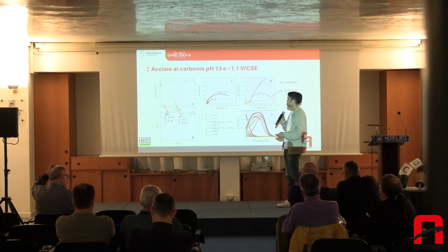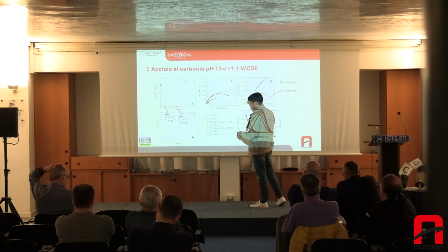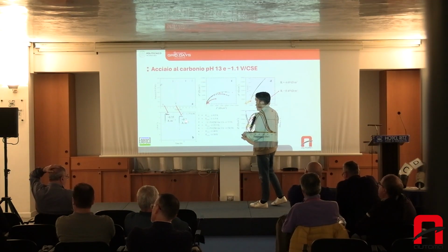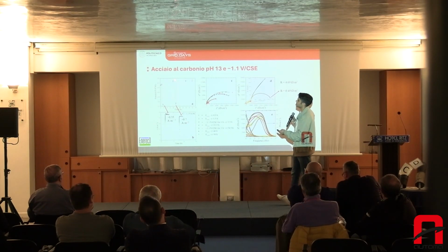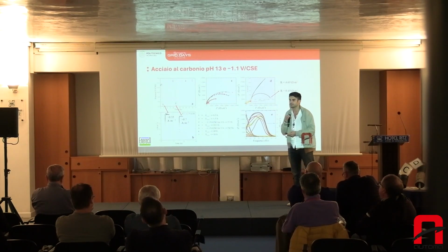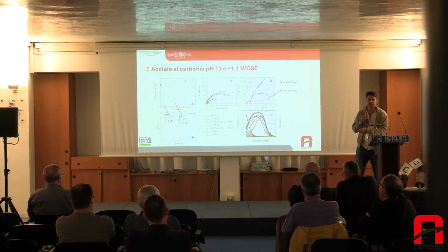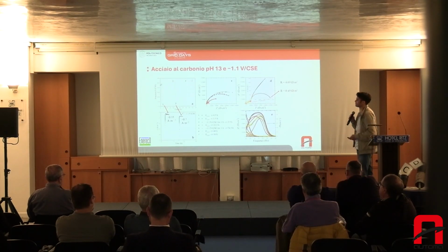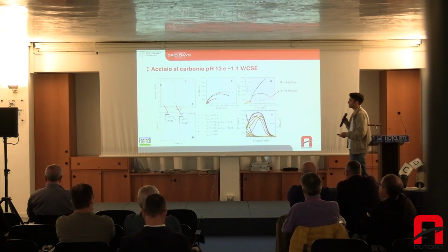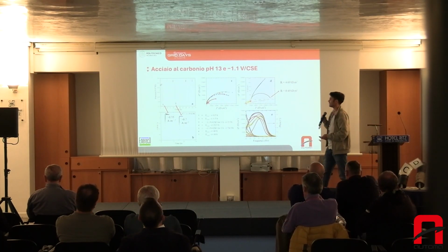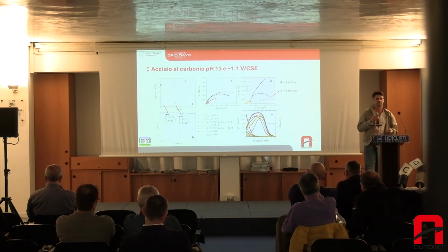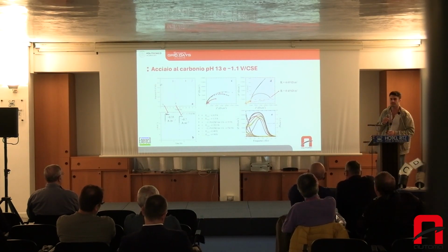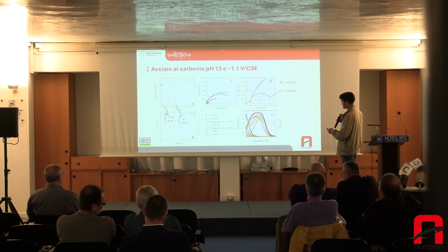In this case, the situation is similar to that of an uncovered tube in water, in seawater. And after several stages of polarization, protection current goes up because it's more difficult to have good potentials for the steel. This brings about important modifications, which is due to the alkaline values that are developed on that steel. And these conditions will then play a significant role if there are some external conditions, like, for example, an interference in alternate current.